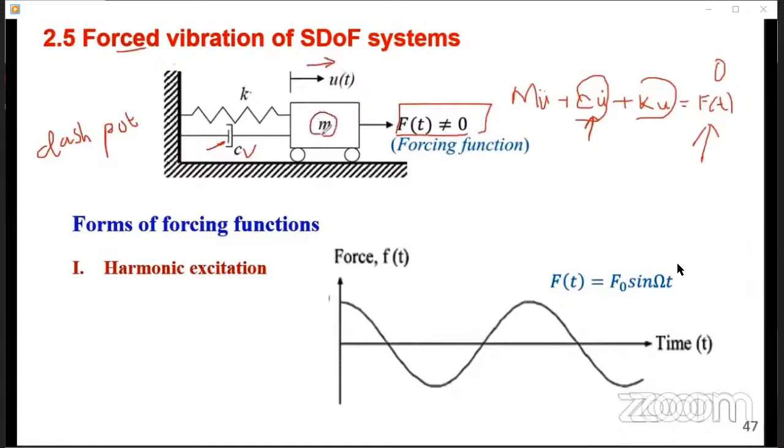Then because of the mass m, remember we talked of D'Alembert's principle. D'Alembert's principle states that a system may be set in a state of dynamic equilibrium. That is, if you want to set a system in a state of dynamic equilibrium, you can add an external force, a fictitious force that is commonly known as an inertial force. I find the statement of D'Alembert's principle to be restating what you already studied in Newton's second law of motion, F equals ma.